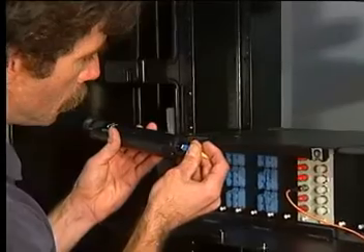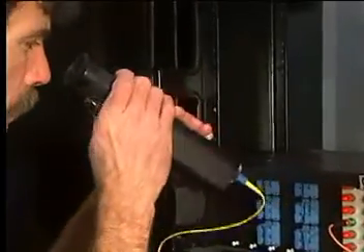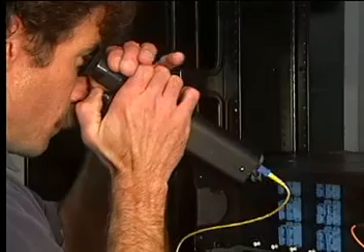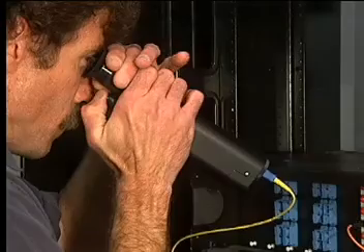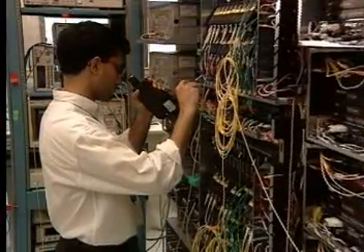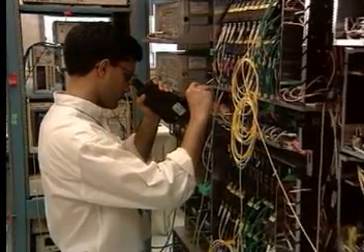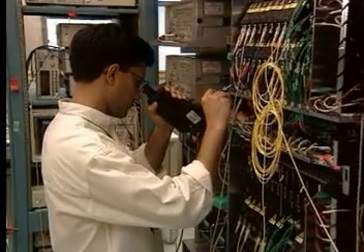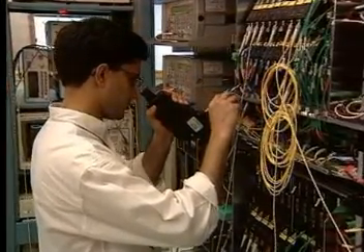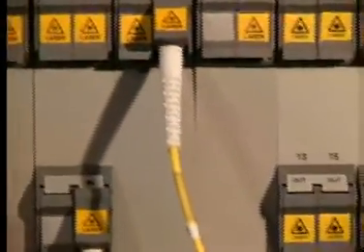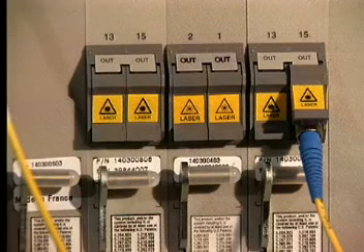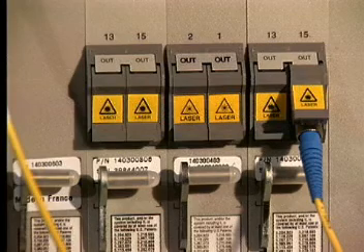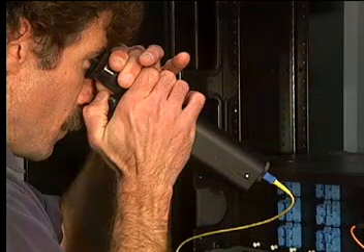The 200 power scope can show sufficient detail when inspecting multi-mode connectors. However, when testing single-mode connectors, the use of 400 power or stronger scopes must be used. When using optical scopes, be absolutely sure that the connector you are viewing is not live. Although many scopes have internal laser filters, the high laser power levels used in modern fiber networks like CATV and DWDM systems can potentially cause instantaneous and irreversible eye damage if the beam directly enters the eye. Never trust your sight to any optical filter.